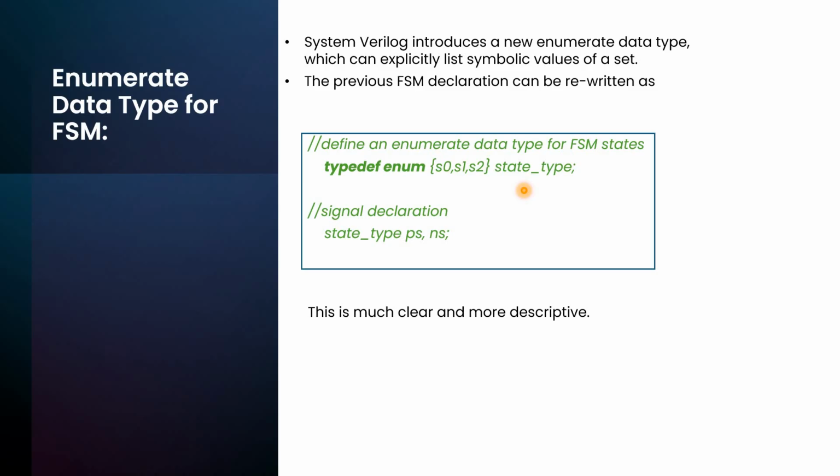So here if you see, we do not have to use the localparam or parameter constructs, and the numerical value for the states will also automatically get enumerated. Default from 0. If you give a particular value to S0, then the values start from that value, incrementing 1 for each and every state.